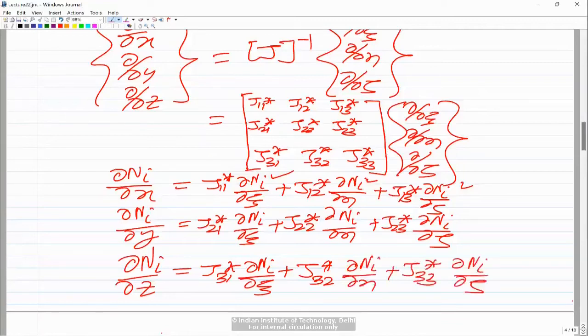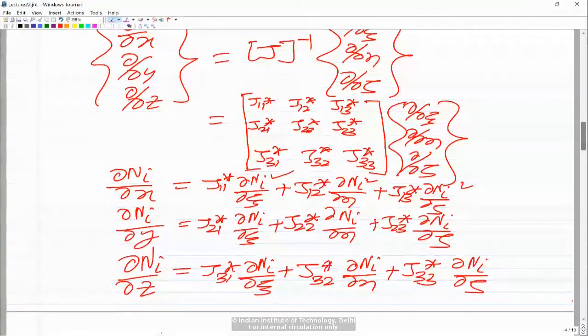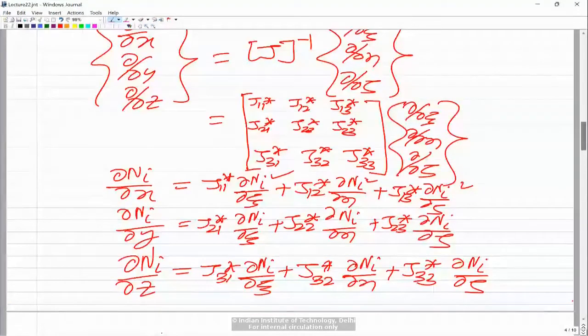So now, once everything is defined, at any given xi, eta point you can express x, y, z in terms of xi and eta, then get the Jacobian matrix, get its inverse, and then define the shape function derivatives with respect to xi, eta, and zeta, and then get their derivatives with respect to x, y, and z. So here, in all these three, I goes from 1, 2, and so on up to 8. So this is for all the shape functions.